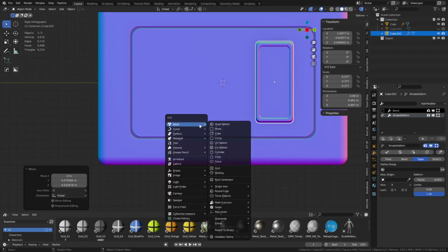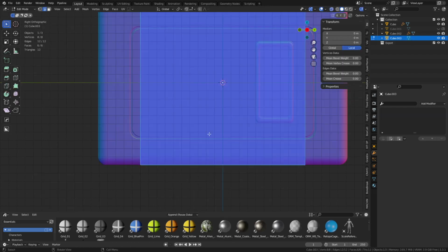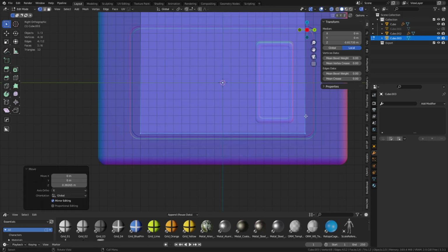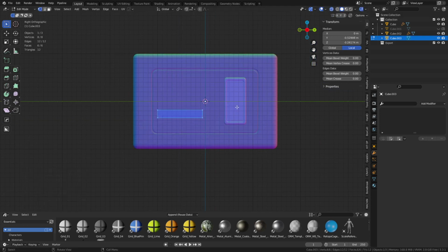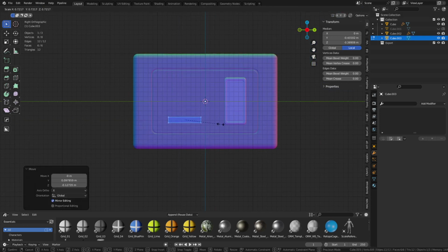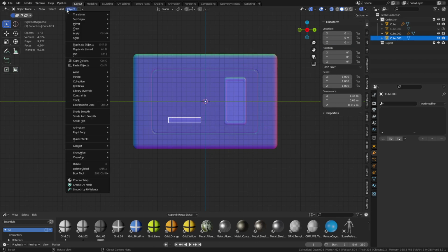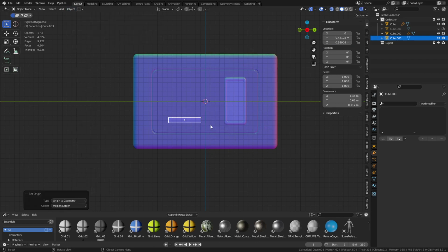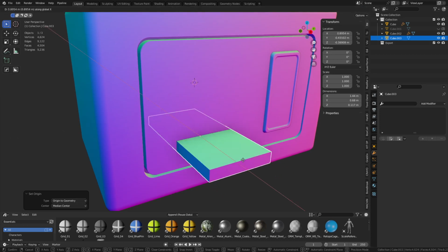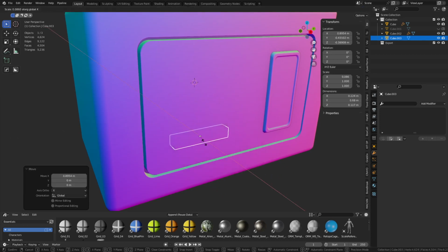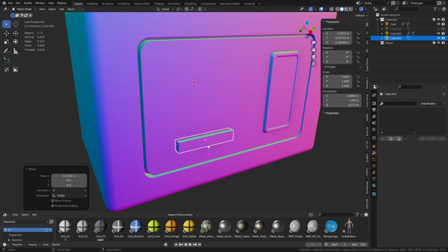Let's go ahead and add a couple other little elements real quick. I'm going to kind of fly through these ones since we got the idea of what's going on here. And let's go ahead and do this. We can place the origin point back to the geometry here. Pull this one out. I'll place it at the surface and just scale it non-uniformly. Control A, apply scale. And now we can do another bevel.